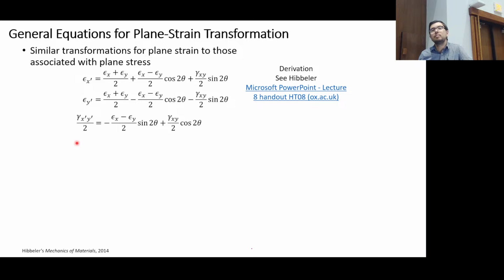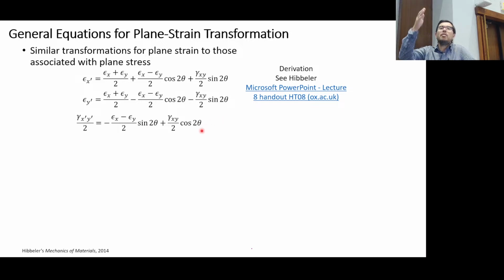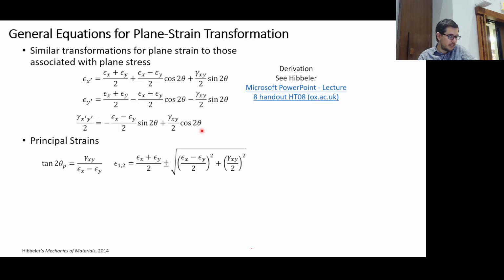Yes? Does the Mohr circle in this case still have the same thing with the 2 theta? Yes. So the theta is still 2 theta because that's over here, right? But now it's just the vertical axis. Remember at that first slide, we said, look, this is the first time I'm saying it's gamma over 2. It's gamma over 2 for that axis, but yes, the angle of rotation is still going to be twice in the Mohr circle, or 2 theta in the Mohr circle, and the material element is just the theta. All right, good questions, good points.